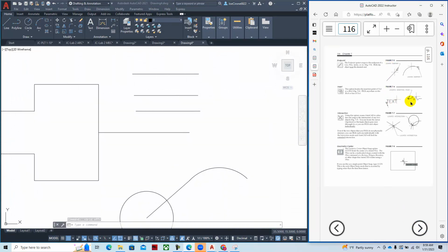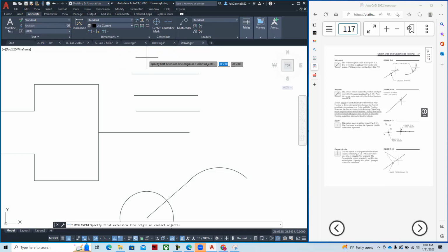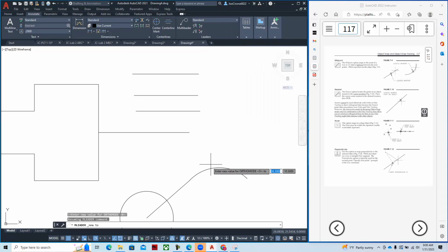And so as we work with these different object snaps, you can kind of see how it will gravitate to different O snaps: centers, midpoints, nearest. I like the nearest O snap a lot if I'm putting in dimensions. For example, if I go under Annotate and I'm putting in a multi-leader, I'll oftentimes go Shift right mouse click, nearest, so that the arrowhead touches the geometry.